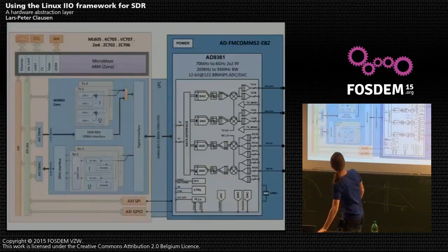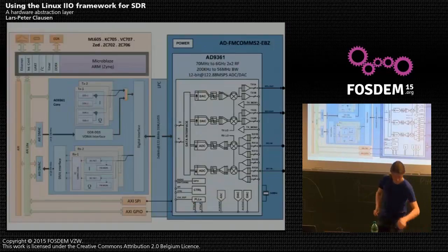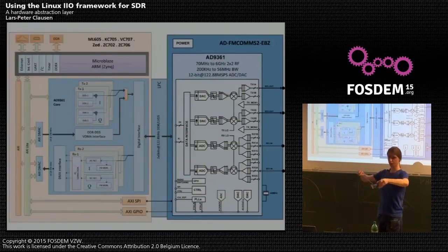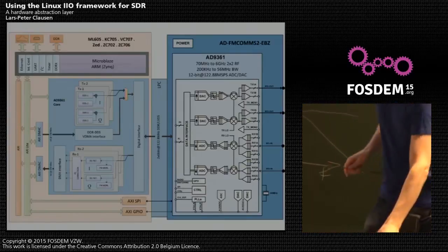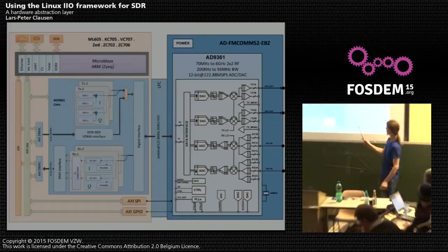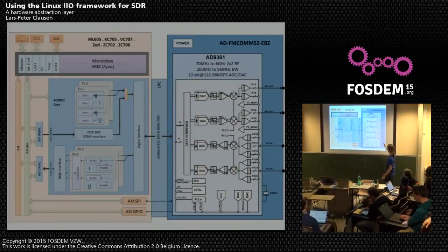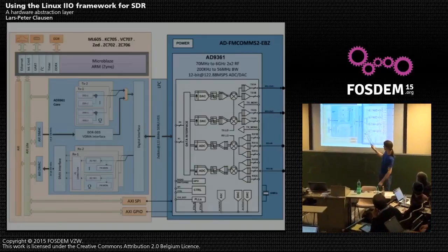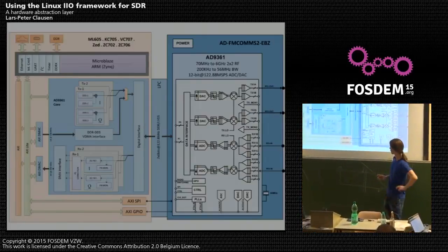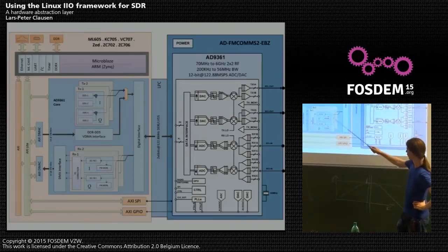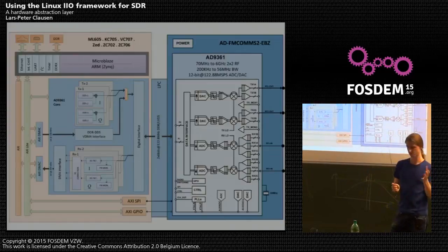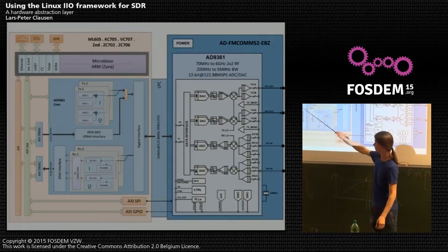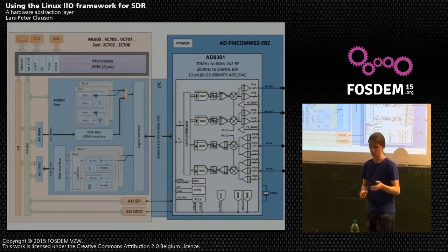And the way, so this is just this board, and there's just a chip on this board, and you typically hook it up to an FPGA using the FMC connector. And this is kind of the system overview diagram. This is the chip itself, which has 2 DACs, 2 ADCs, and so on. Then we stream the data over into the FPGA, and we have a small processing pipeline by default, which just does some correction and calibration of the data, and then sends it to a DMA controller, one for transmit and one for receive. That's what we've seen earlier.